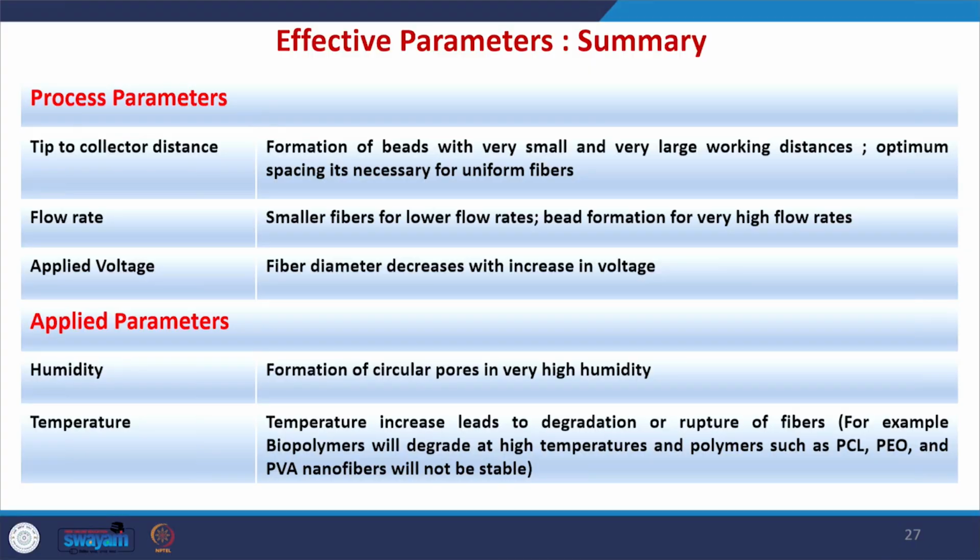Let us see the summary of process parameters and applied parameters. In the process parameters, the first one is tip to collector distance. There will be a formation of beads when you are keeping the distance very small or very large.